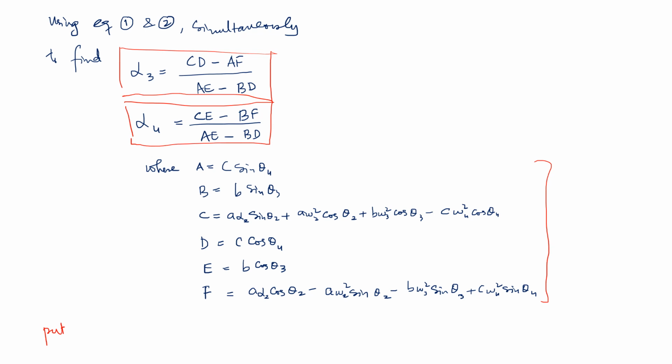plugged in expression A. And if you recall, in the expression A there were three subcomponents. There was acceleration of point A that was given, there was acceleration of point B in relation to the point A, and then you have acceleration of point B indicated over there. And obviously in all of these expressions, you're going to have the normal component and the tangential component added in it.